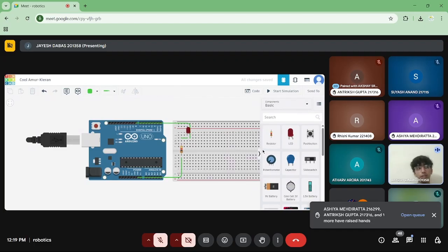So when we are using a motor, yes, we can use a motor on an analog pin as well. But when we are making a big project, what usually happens is that the number of analog pins is less. We need more. So we prefer using motors or any other type of actuator or sensor on digital pins, and keep analog empty. Okay, thank you.